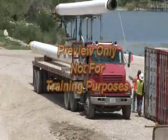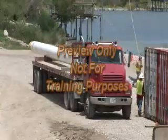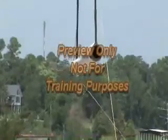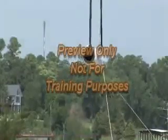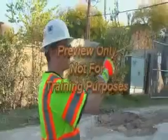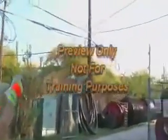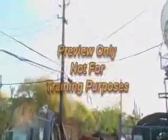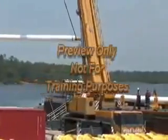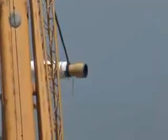Keep the load close to the ground. If necessary, use a tag line to guide the load and minimize rotation. Never wrap tag line around your hand or body. Use a non-conductive line. Keep in mind, a wet rope can and will conduct electricity. Always consider weather and wind conditions before beginning the lift.